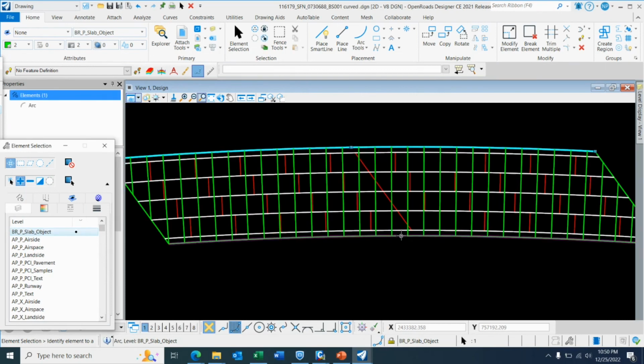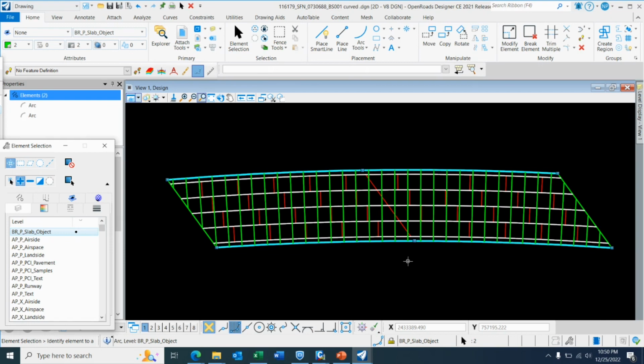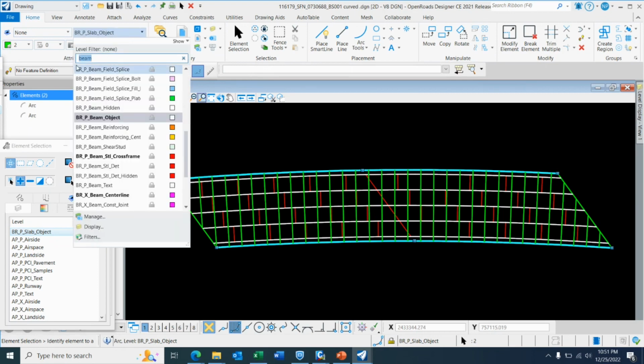Let's now talk about the edges of deck on each side. This one right here and this one. These are not cross beams, but we will still keep these in our model to represent a complete bridge model in Midas. These outer lines will not contribute to either rigidity nor weight. We will make their weight 0 and area a very small number, which is approximately 0 because we can't input area of any section as 0. We will also use a different layer for these outer lines. So I'll just put this in default layers.